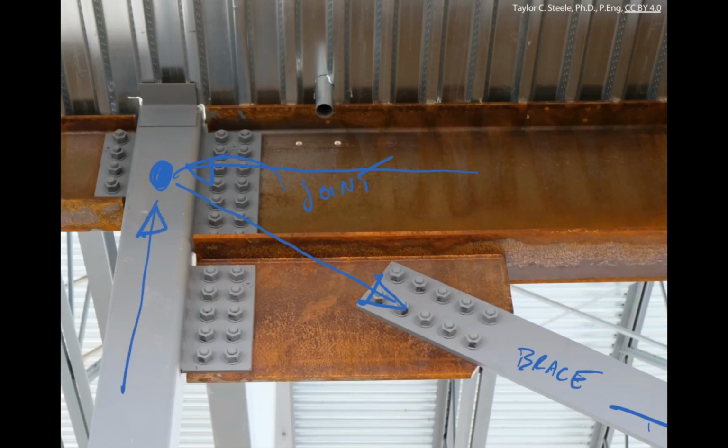When we're arranging our bracing, we tend to want to make them what we call concentric. Concentric means that the loads in those braces all pass through more or less the same point so that we can apply our method of joints for our structural analysis, and then we expect those structures to behave the way that we think they will in the field. So this is an example of tension-only bracing. This is a flat bar, right? We talked about that in lecture 2. Flat bar is a common kind of structural steel member to use in a tension-only bracing situation because there's not much compressive resistance to a flat bar like this.